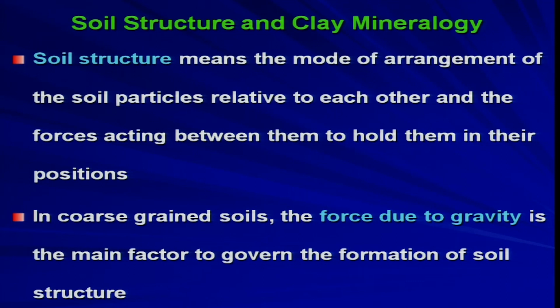In coarse grain soils, the force due to gravity is the main factor governing the formation of soil structure. It is very simple. If you fill a container with sand dropped from different heights, you will see that the soil structure or the packing of the sand is different, because the force due to gravity is the main governing factor which defines the soil structure.